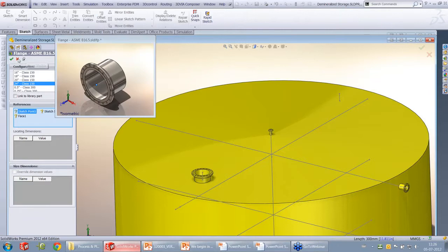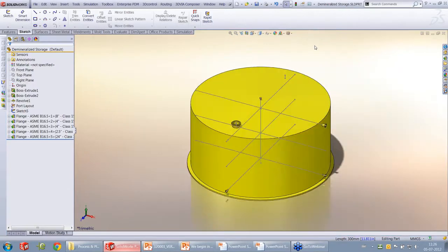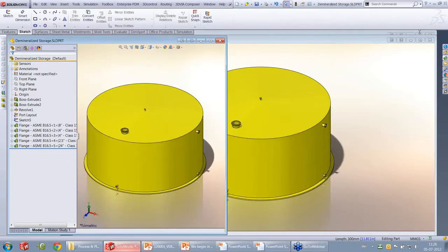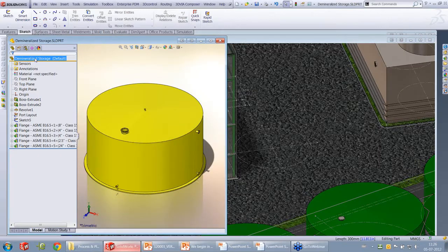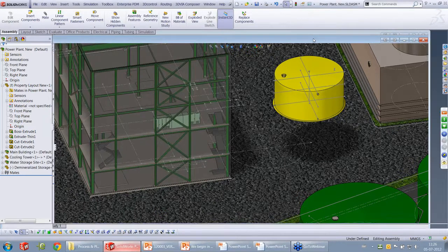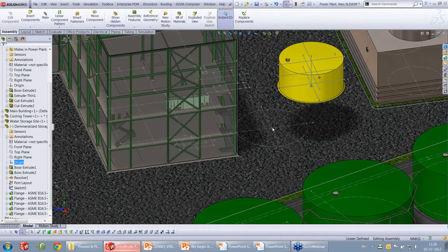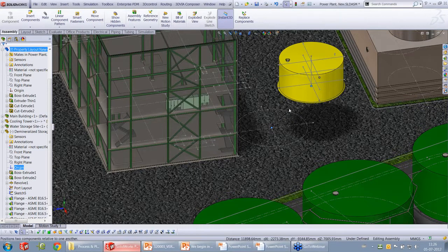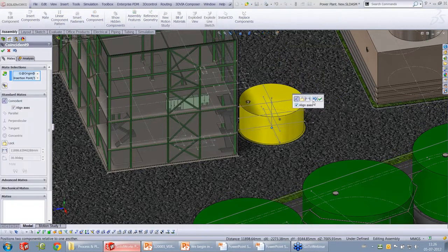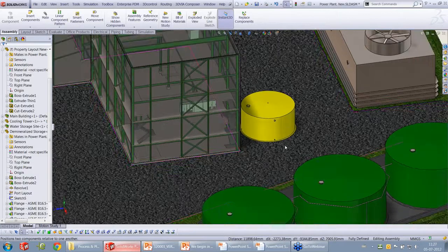So we are almost done. We can turn off the sketch and bring this into our SolidWorks assembly. It's as simple as a drag and drop, and locating it can be done in the similar fashion that we did earlier. Just pick the origin, pick the reference point on your 2D layout, and align the axis so that it stays put. Let me turn off the sketches.